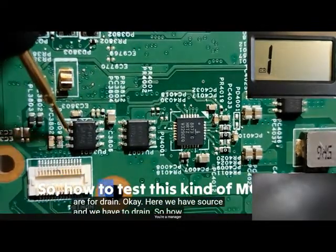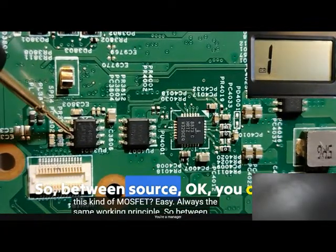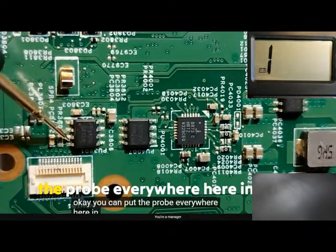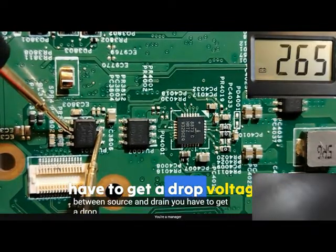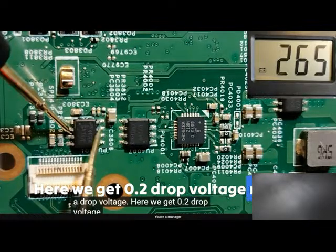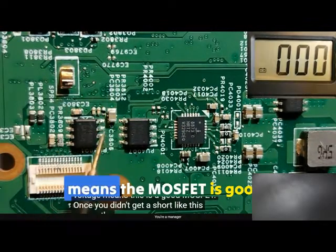So how to test this kind of MOSFET? Easy, always the same working principle. Between source, okay, you can put the probe on any pin of the source. So between source and drain, you have to get a drop voltage. Here we get 0.2 drop voltage, means this is a good MOSFET. Once you don't get a short like this, it means the MOSFET is good.